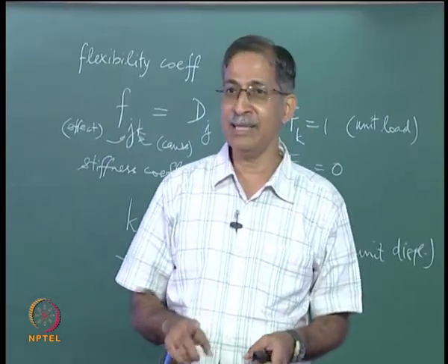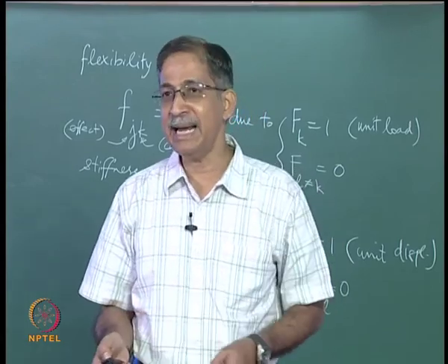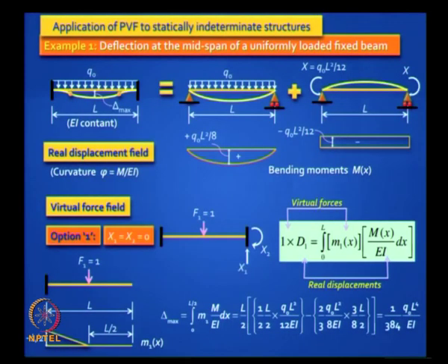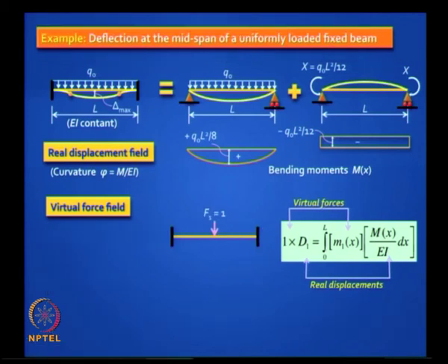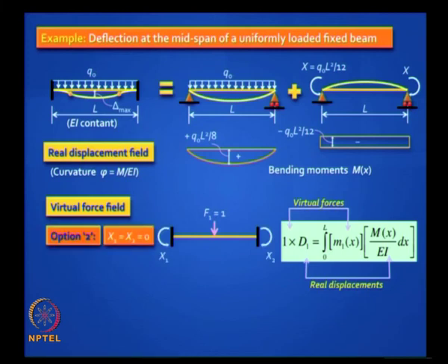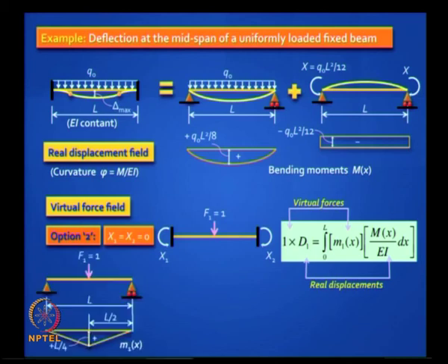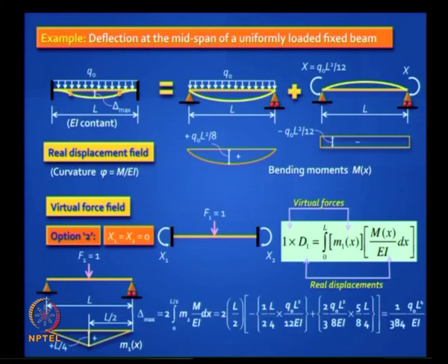Now what is extremely interesting is, you could have chosen any statically admissible diagram. So we will just see an alternative where we will treat the primary structure now as simply supported. That means here x1 and x2 is 0. So now I am dealing with a simply supported beam. Now my small m diagram has changed completely, and if I do the multiplication, you can check this out, I get exactly the same answer. This is really a mind blowing discovery.